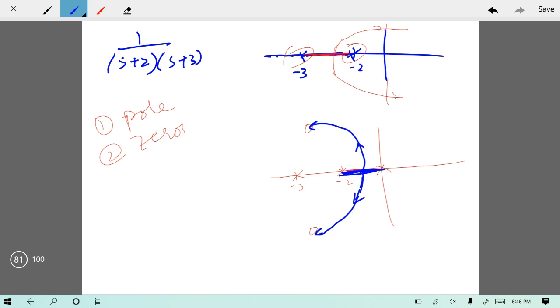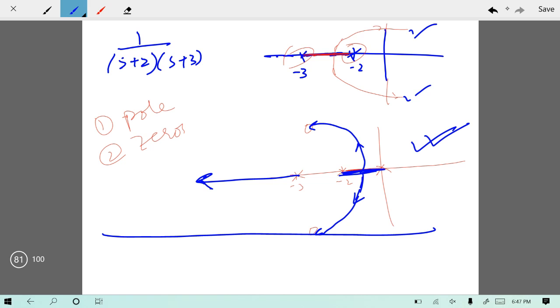So earlier two poles were going towards infinity, and they were becoming the source of instability of a system. However, by introducing a PID controller, you have given a terminating point to these poles in left half plane. So these poles, instead of going to infinity in the right half plane, instead of having a tendency to make a system unstable, they now always remain in the left half plane, and system will never become unstable. For this pole, it will go to minus infinity, and your new root locus will be this.